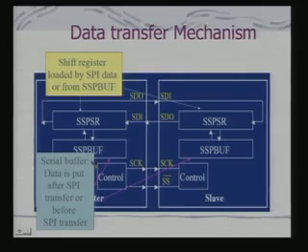When you are actually transmitting, the processor will load data onto SSP buff, and then SSP buff will load that data onto SSPSR. So, it is parallel out from here and parallel in to SSPSR, and then it is shifted out when the data is being sent. So, this is the basic mechanism involved here.